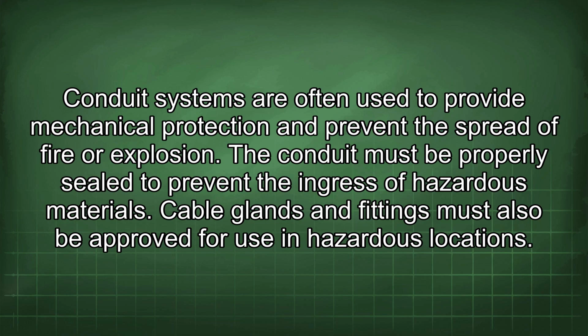Conduit systems are often used to provide mechanical protection and prevent the spread of fire or explosion. The conduit must be properly sealed to prevent the ingress of hazardous materials. Cable glands and fittings must also be approved for use in hazardous locations.